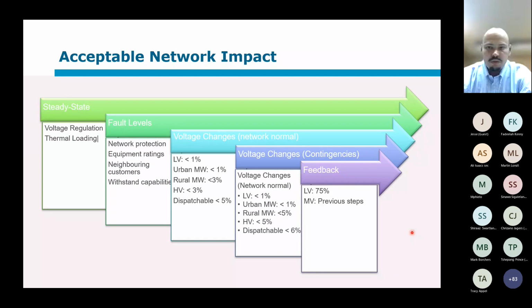So the DC would already be blocked by that transformer, which in this case would belong to the customer, so it's not the distributor's concern anymore. Harmonics, if you connect at medium voltage, are probably also mostly filtered at the low voltage transformers, or you have better emission limits, which will reduce that impact. But once again, it's a good idea to discuss that with the transformer supplier.